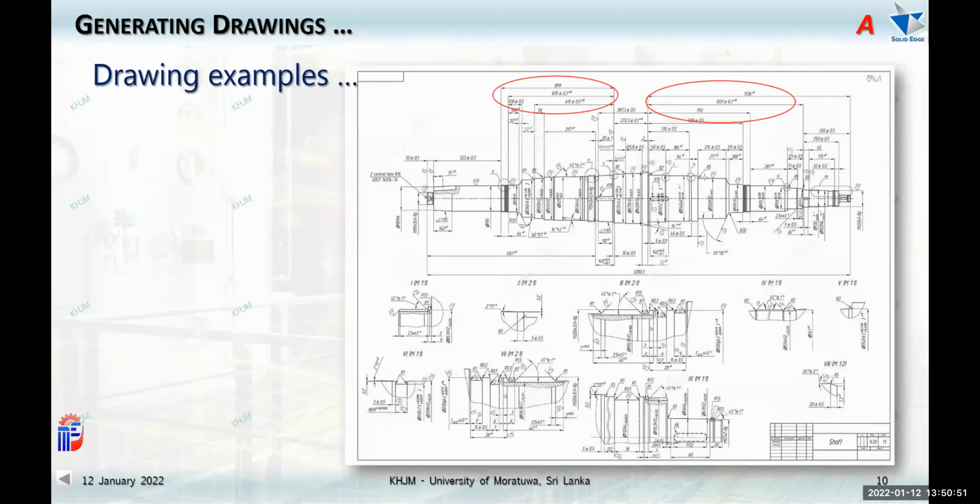Why? Because you are making a continued dimension. The dimension is continued from where you stopped from the previous one. Right? Otherwise, you can see all these details are given. Details cannot be shown in the original, and if you try to do so, it becomes very ambiguous. So you can't do that. Look at this, how many steps are there, and look at even the tolerances. Wherever necessary, you have to give the tolerances as well. So please keep these things in mind.